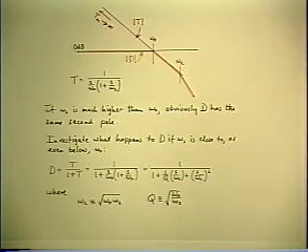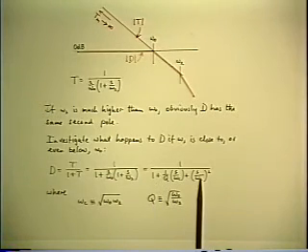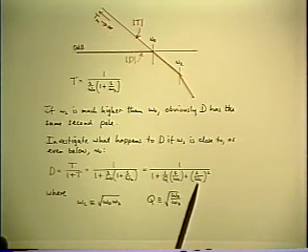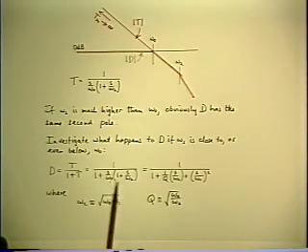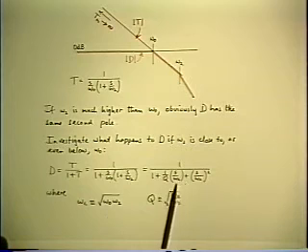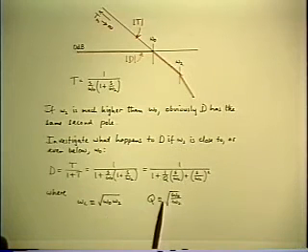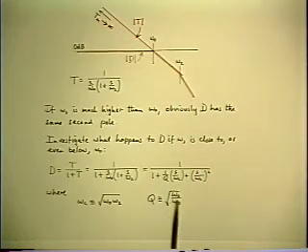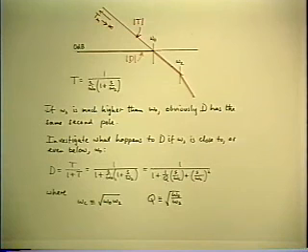And now you should have that automatic response. Whenever you see a quadratic, find its corner frequency and its Q factor. So write it in the normalized form, and in order to do that, you have to define the corner frequency omega c as the square root of omega 0 omega 2, and the Q factor is root omega 0 over omega 2. That's exactly the same quadratic that we spent a lot of time talking about in relationship to an RLC filter.